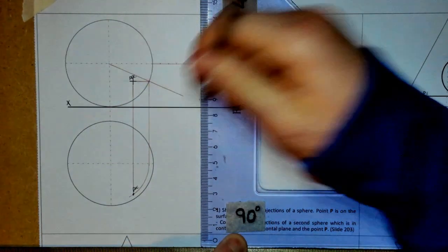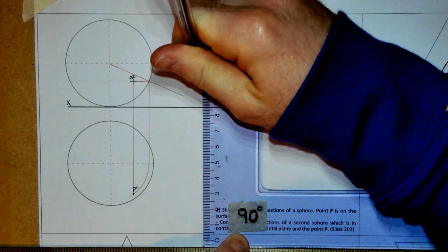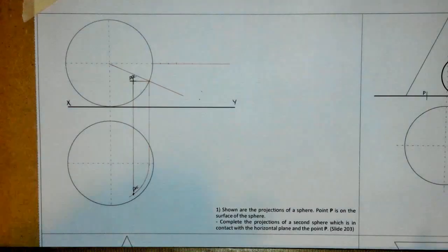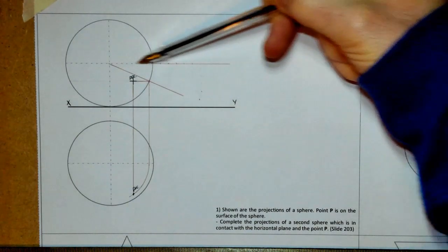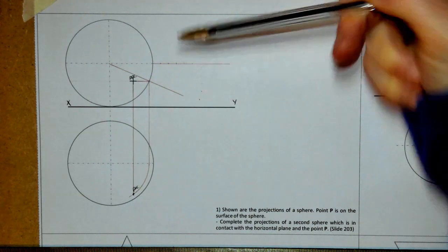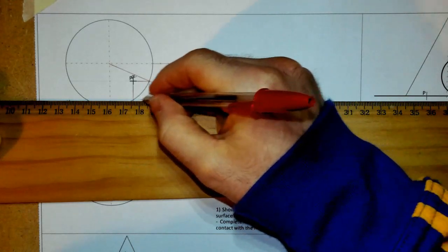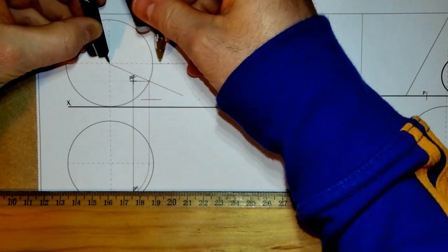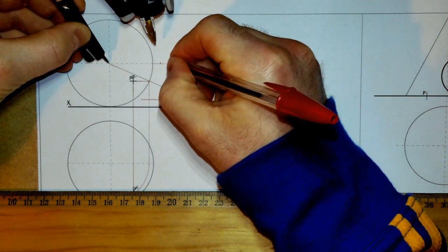So I'm going to go 5, 10, 15, 20, 25. Essentially I'm taking the same distances out from each one. I'm marking 5 millimeters up from the XY line, and I'm marking 5 millimeters out from the radius of the large sphere. 5, 10, 15, 20. Just watch this here. If I mark the first 5 and make a line like that, and go to the center of my large sphere and go to the first 5 millimeters out, you can see that little point there. I'll make them a little bit more clear so you can see them a bit better.